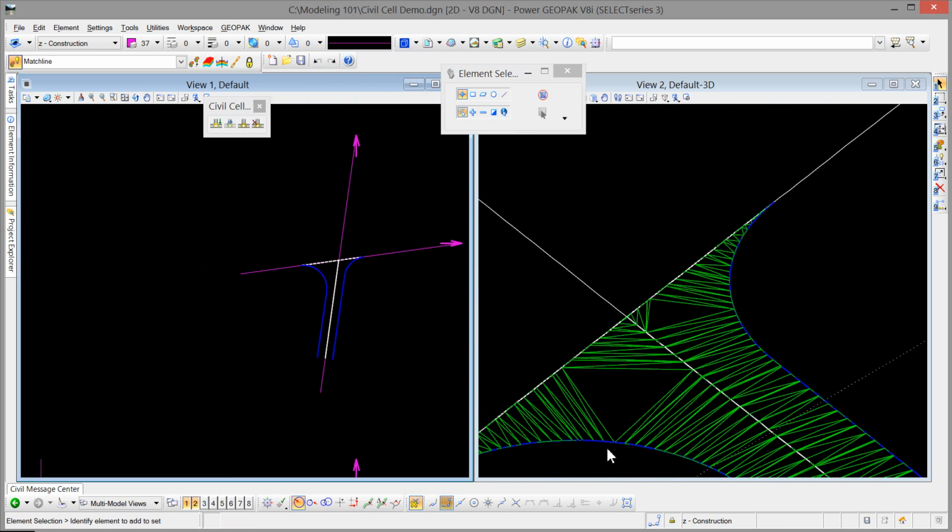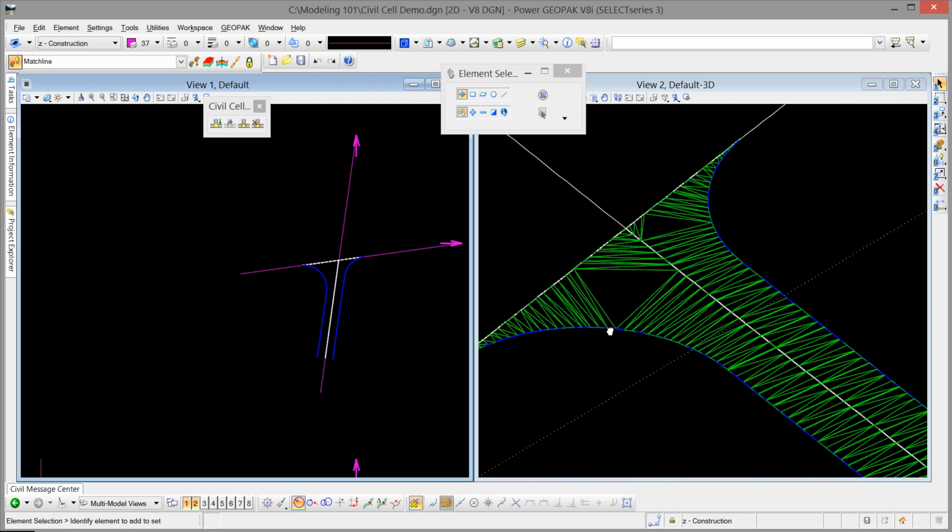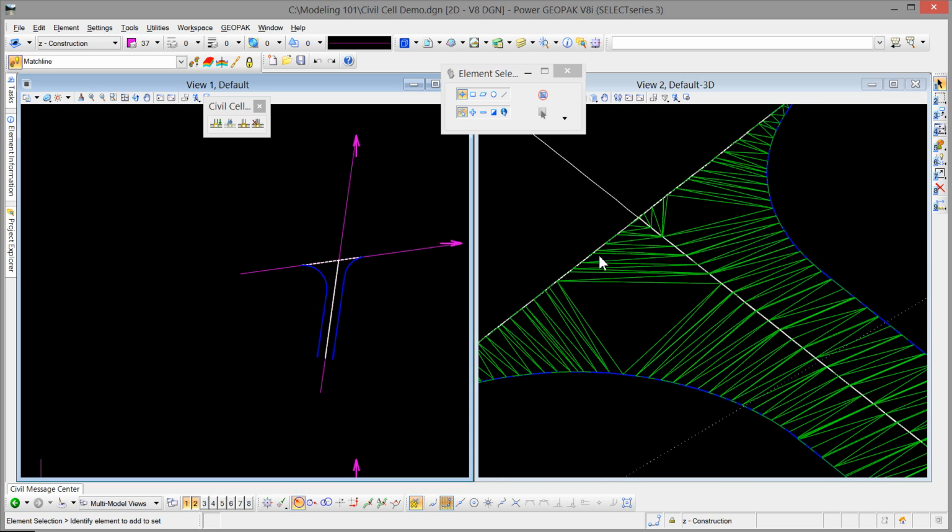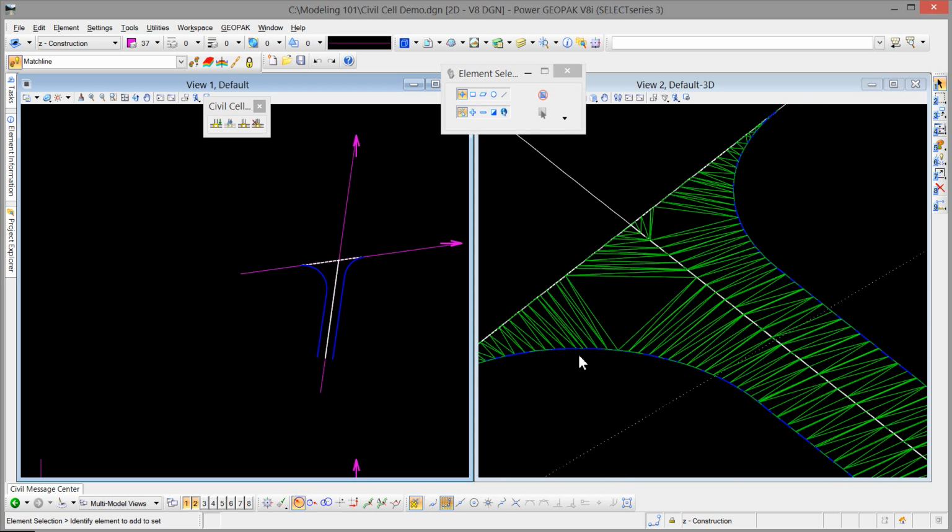or accurate. Now the problem is it also requires more processing horsepower. So yes, I could set this to every inch, and I could set these to 0.000001, but I have just made a monster terrain that I got to process every time I clip the corridor. Okay, so just use common sense.